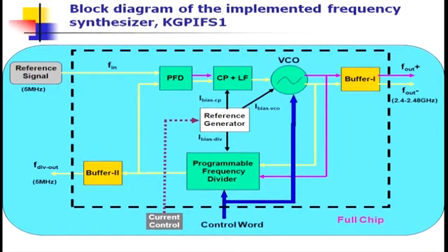So, if there is an up current and a down current mismatch, that will cause a permanent offset in the phase, and that will harm your lock-in characteristics. Therefore, you need fine tuning to avoid this mismatch. Some controllability has been introduced in this bias control generator. How? Because you introduce some extra current to compensate for those variations.